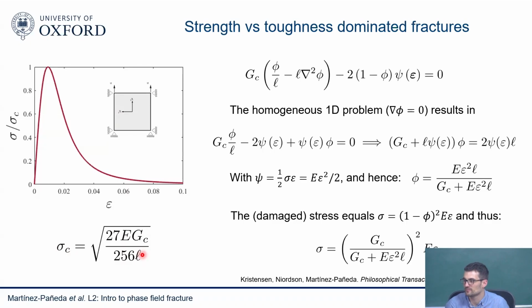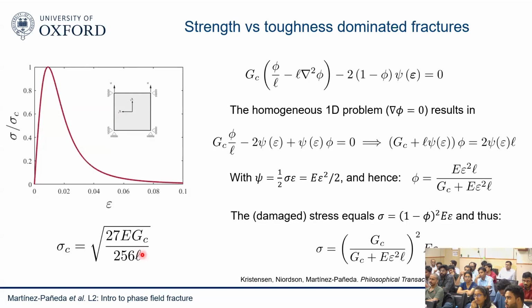Usually in ductile materials, the fracture process zone is smaller. But if I talk about quasi-brittle material or something like that, in this case we have a sizable fracture process zone. So should the L then be higher, and can we take some number of elements inside L or something like that? Is there any relation between L and element size?